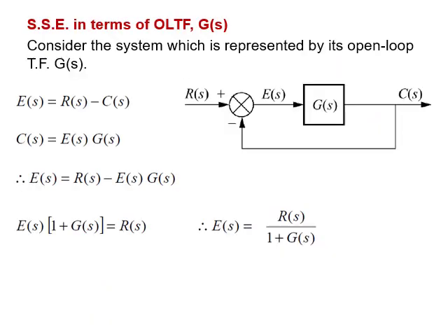Now, in terms of G(S), the system is unity feedback. What does it mean here? It means the information I have about the system is G(S), but G(S) is placed in a control system with unity feedback, as you see here. So the error is going to be this value. If the case is like this, how am I going to evaluate it? We are going to evaluate it by calculating E(S), I mean the equation for E(S).